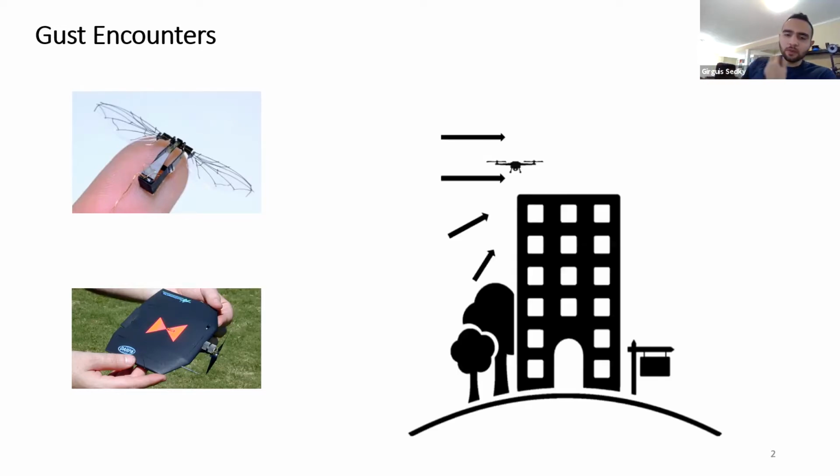The problem with going smaller and smaller in the design of air vehicles is that you end up entering the low Reynolds number regimes, or aerodynamic regimes, where the flow easily separates. In conventional aircraft, the vehicles are big enough to be in the high Reynolds number regimes, where the flows have more energy to stay attached to the wings.